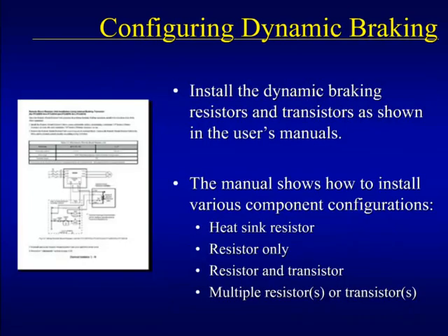Once the dynamic braking components have been received, install the dynamic braking resistors and transistors as shown in the user's manual. The user's manual provides installation instructions for all of the available component configurations.